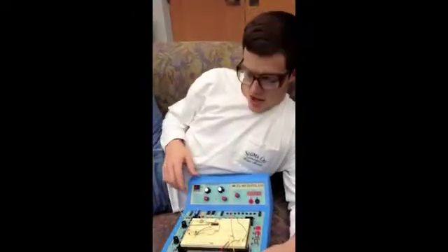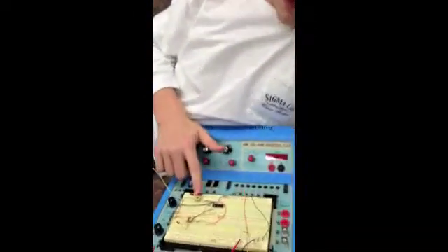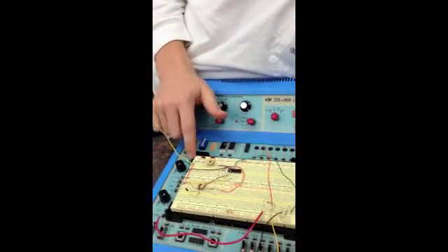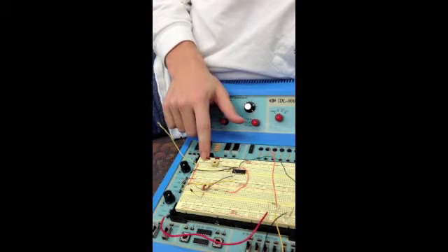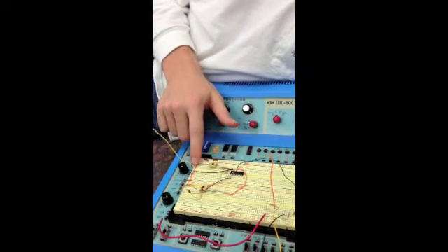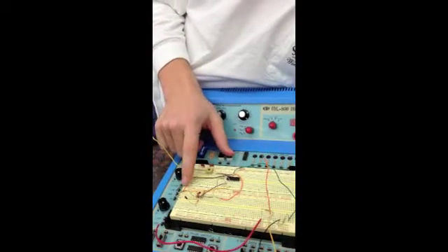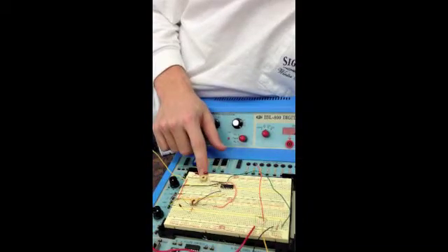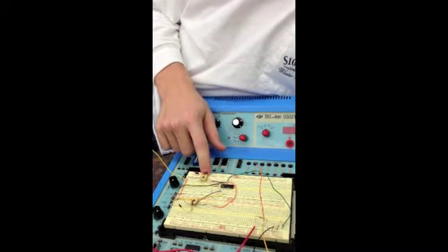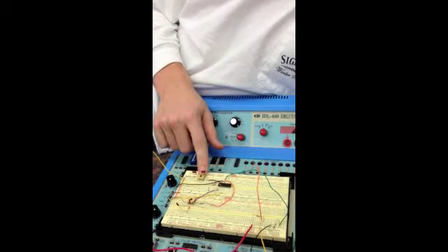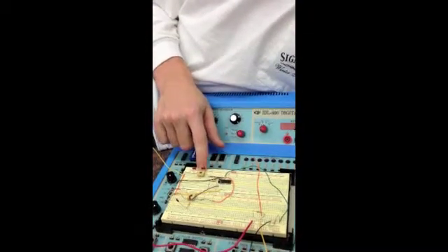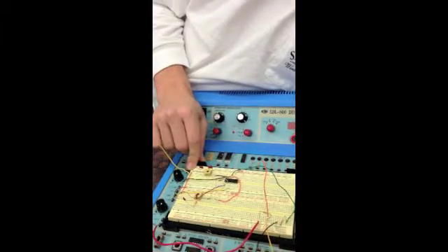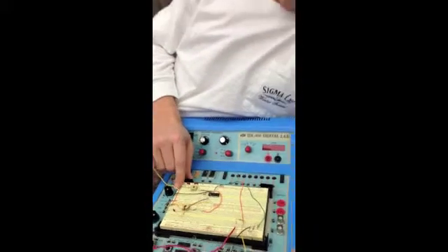The reason for changing these values of the capacitors and R5 was that initially we had issues with current from low frequencies flowing into the treble part of the circuit and currents from high frequencies flowing into the bass. The presence of these currents interfered with the amplification, especially for the treble part, where we had a good deal of difficulty getting sufficient amplification and a sufficient degree of cut. We didn't have as much problem with the bass. But once we were able to find values that worked, we were able to settle on them and get the amplification that you will see in the Bode plots.